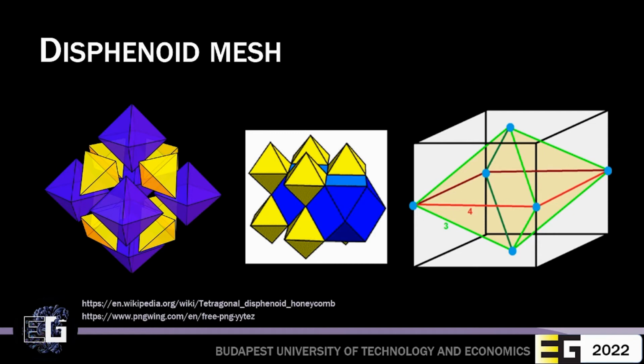Parallel execution becomes possible if the elements are sorted in geometrically disjunct sets with no 2 tetrahedra from the same set sharing a vertex. We achieve this with the tetragonal disphenoid honeycomb. The vertices are aligned on a body-centered cubic grid which is easily converted into 2 3D arrays of GPU representation. Each vertex has 24 connecting elements, and 12 of these elements make up a shape that tiles the space when aligned on a cubic grid. This defines 12 classes of tetrahedral elements. If we further split them into even and odd elements in a 3D checkerboard pattern, we obtain 24 geometrically disjunct classes.